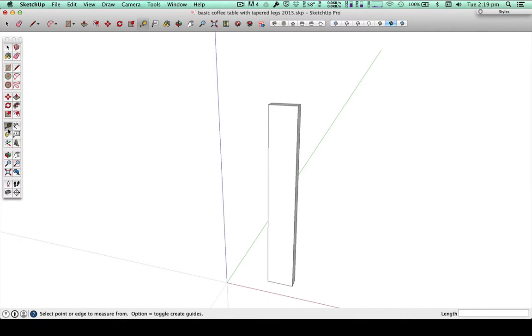So I've gone over here to the tape measure, click that. Instead of clicking the tape measure on an edge or a corner, an end point of a line, I'm actually going to click it on a line and click and hold and drag down. Now you can't probably see, there is a blue on this line, so it's telling me I'm on the blue axis, and I'm just going to let it go anywhere. So I can have my fingers back off the mouse and just type in 60. That now has popped that line exactly 60 millimeters from where I started.